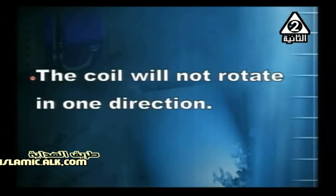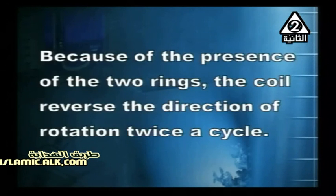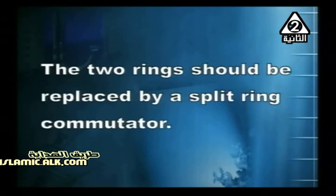Okay, there is something wrong here. The coil will not rotate in one direction. You know why? Because of the presence of the two rings. The coil reverses its direction of rotation twice a cycle. Each half cycle, it reverses its direction of motion. So, to correct this, the two rings should be replaced by a split ring commutator.